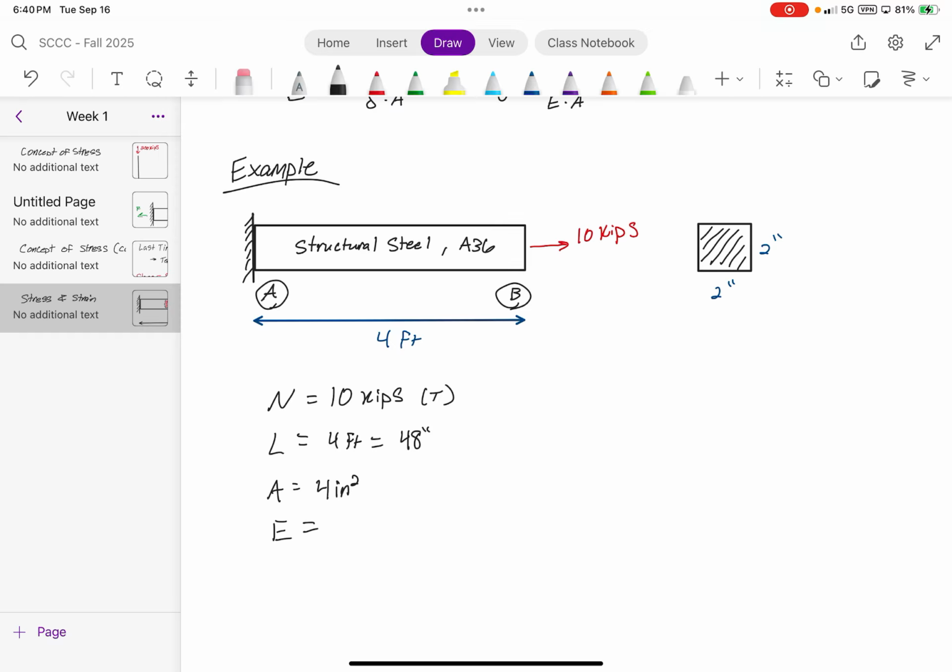What is it? Not 29 psi. You'll notice right where it says elastic modulus, or modulus of elasticity, there's something right underneath that. Not GPa, you're looking at the metric. Keep it on the yellow tabs since we're dealing with imperial. What does it say? 10 to the 6th, which means that whatever value is tabulated within that column, multiply it by 10 to the 6th.